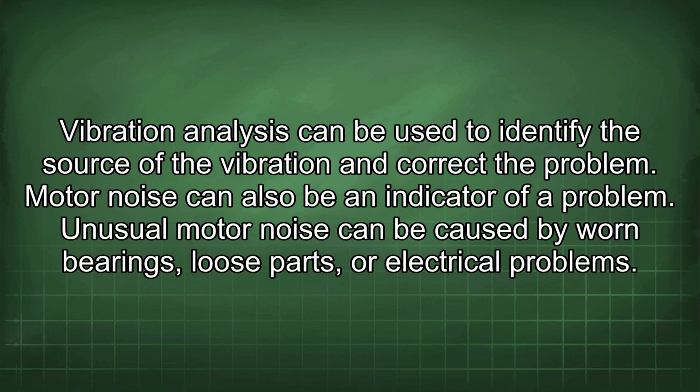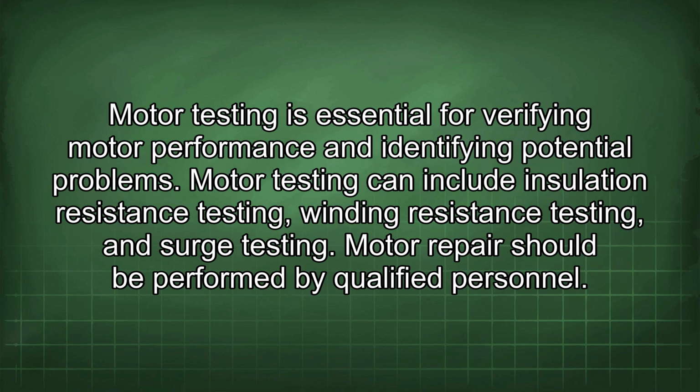Motor noise can also be an indicator of a problem. Unusual motor noise can be caused by worn bearings, loose parts, or electrical problems. Motor testing is essential for verifying motor performance and identifying potential problems. Motor testing can include insulation resistance testing, winding resistance testing, and surge testing.